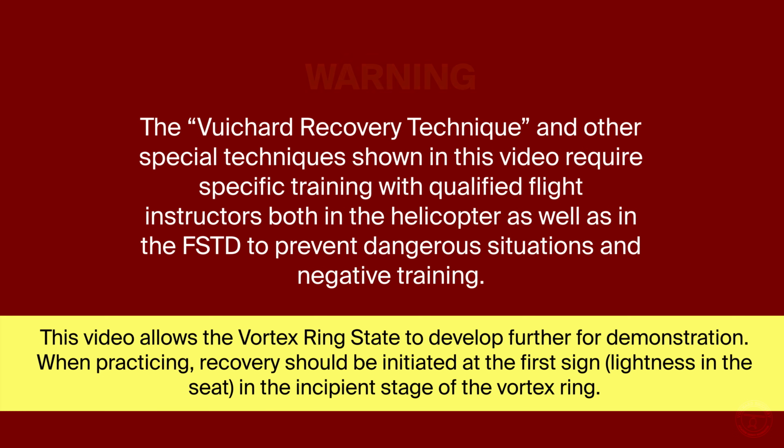This video allows the vortex ring state to develop further for demonstration. When practicing, recovery should be initiated at the first sign, lightness in the seat, in the incipient stage of the vortex ring.